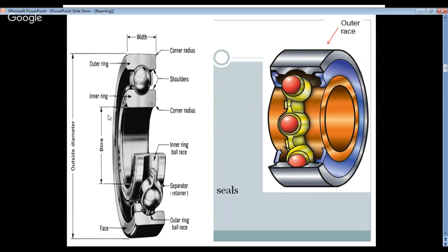The shaft design depends on various parameters like material of the shaft, load offered on the shaft. This load may be bending, maybe weight of the power transmission device, torsion. So shaft is designed basically on the equivalent bending moment and twisting moment formula. When shaft diameter is designed, on the basis of that, a bearing can be selected.